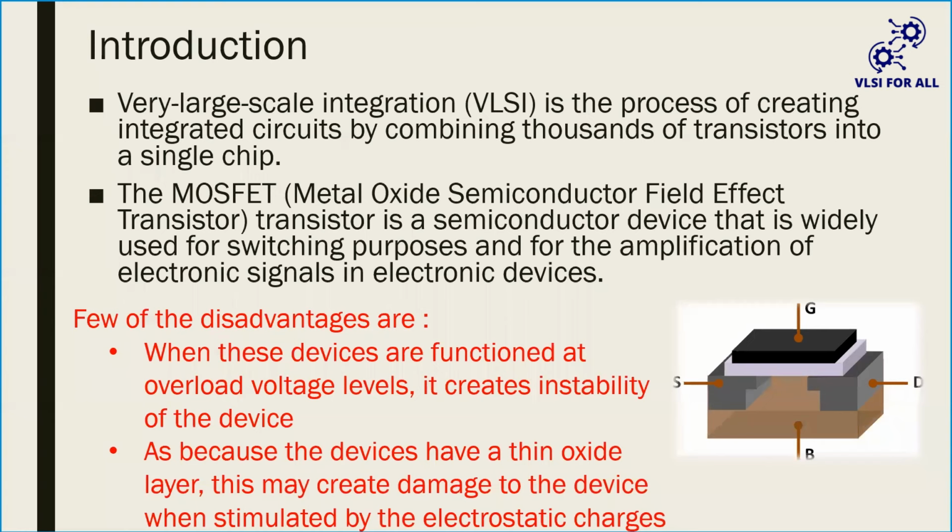Now, coming to the point, if you take a stable input of logic 1 or logic 0 in a CMOS inverter, suppose you take logic 0, PMOS becomes on, but NMOS becomes off. So there is no connection from rail to rail, VDD to ground. If you take the input as logic 1, PMOS becomes off and NMOS becomes on. Whether the output is logic 1 or logic 0, we are least bothered. Here we are bothered about static power dissipation.